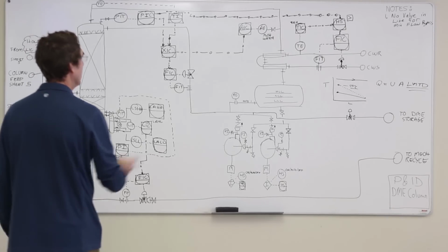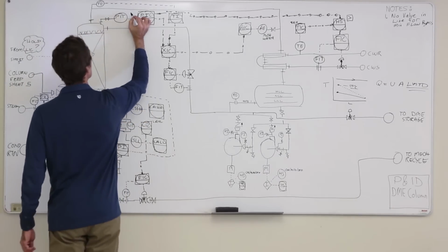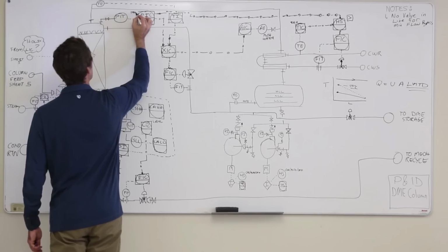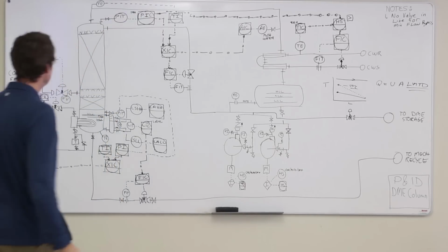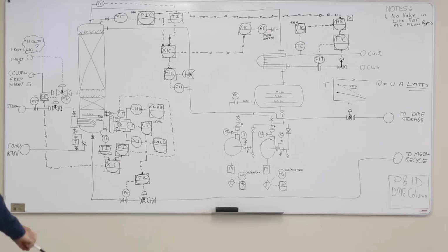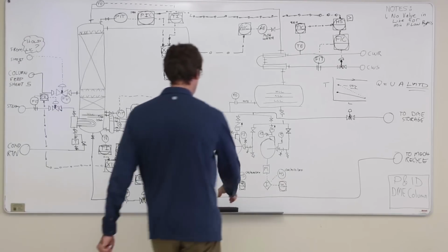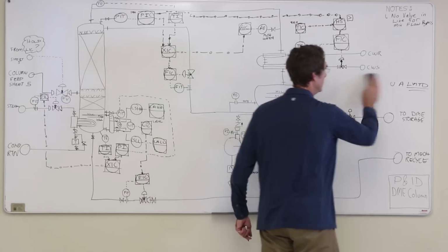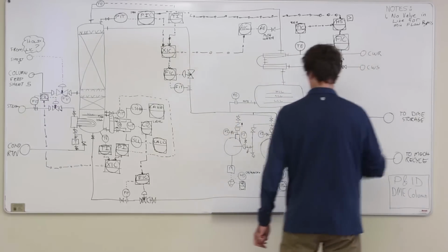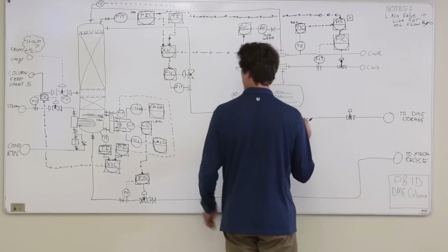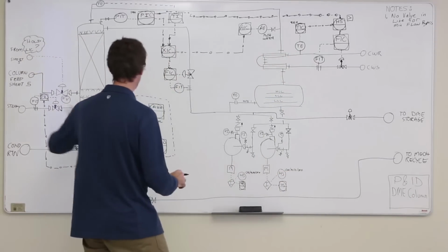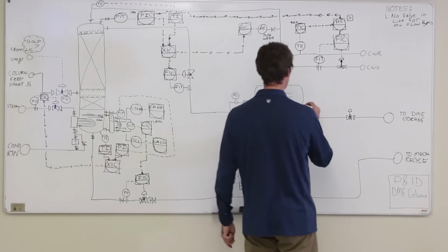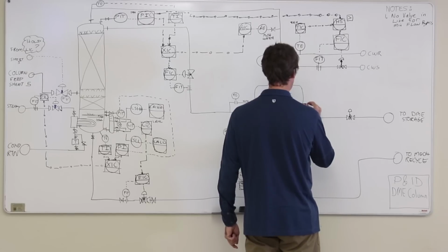And we should definitely need alarms on almost everything. So we definitely want a pressure alarm high on here. Okay, so we are missing still the level control on the tank. That one's pretty straightforward. There's nothing like the inverse response that's happening on here. This one's just pretty straightforward.